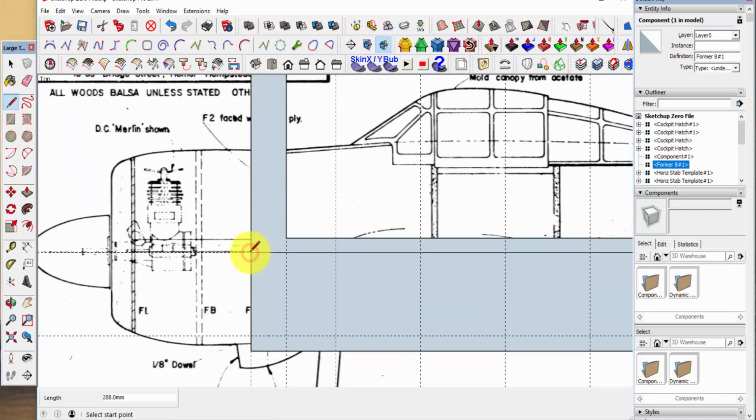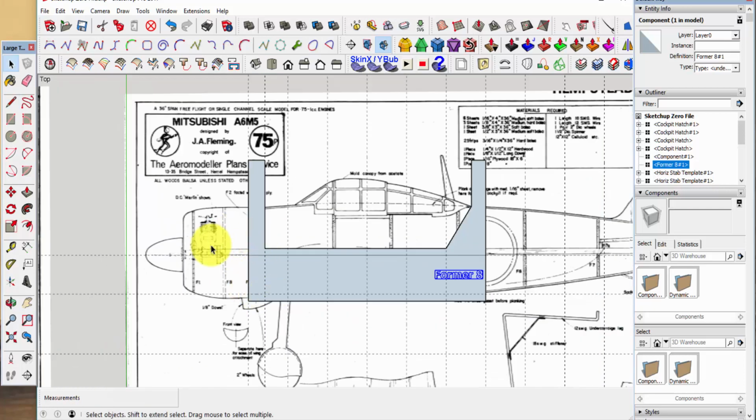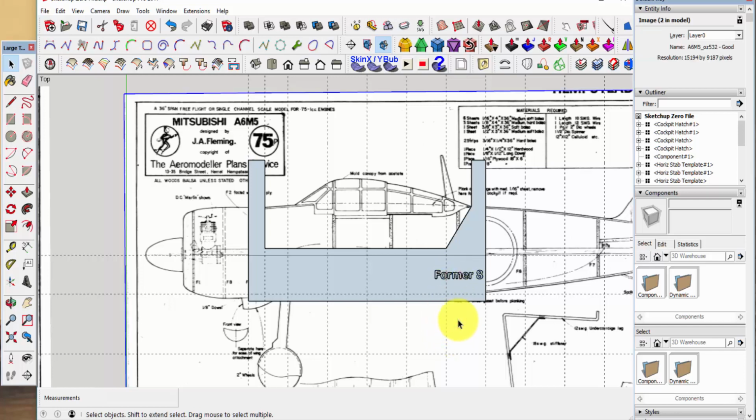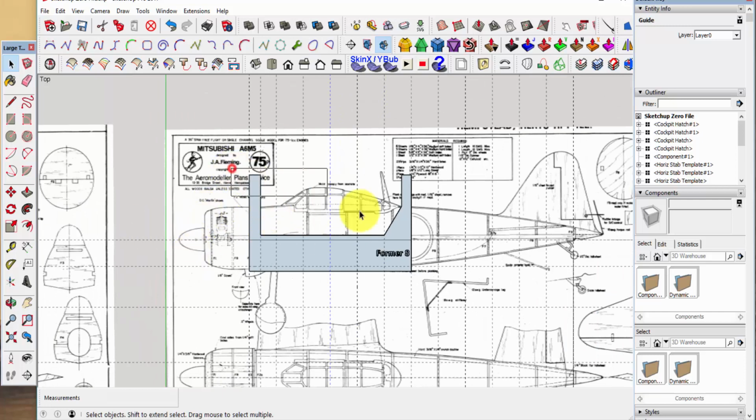This is going to be the most important one right there. That's going to align with the fuselage datum line. Again, the hot wire will enter here, come to the bottom, it'll move aft, up the slope, and out. And then this will just lift right off. Okay, once again, we're going to make sure this is exploded, because we don't really want that to be a component any longer.